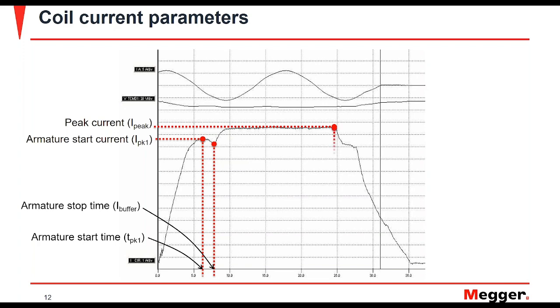And as well, I have to see how long the mechanism takes to fully operate the breaker, because these times are important for me to see if I have a problem within the mechanism of the breaker, like a mechanical problem, bad lubrication, or stiff hydraulics or springs, or my trip coil itself has a bad winding resistance, or some shorting inside the coil, or the armature inside the coil is stiff or has bad lubrication.